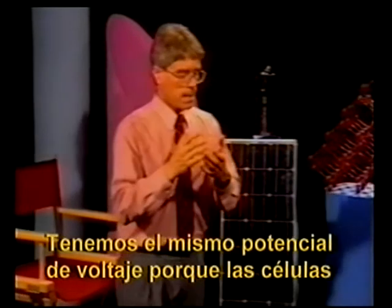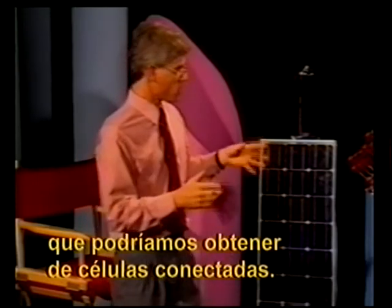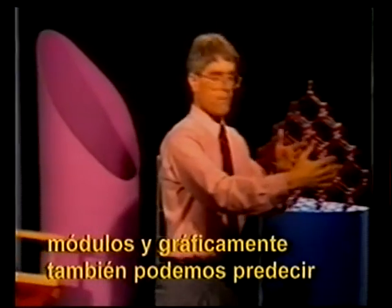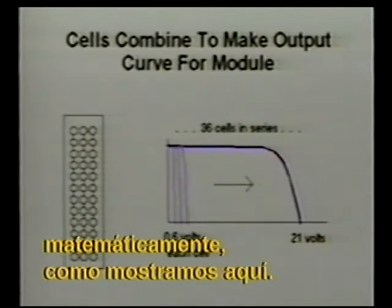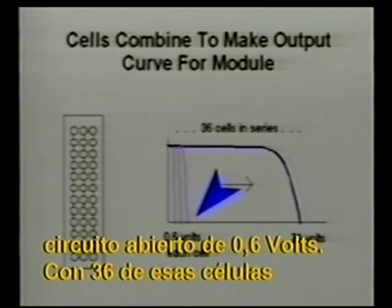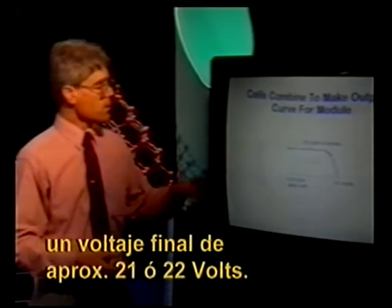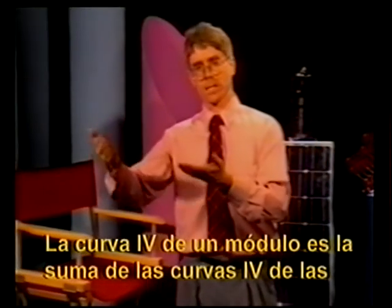So what we can do is physically connect cells together into modules, and then graphically we can also predict the result of that many cells graphically and mathematically, as we show here. An individual IV curve for a cell might have a short circuit current of about 3.4 amps, an open circuit voltage of about 0.6 volts. If we have 36 of those cells added together, we have 36 IV curves added up for a final voltage of about 21 or 22 volts. So the IV curve of a module is just the sum of the IV curves of the individual cells.